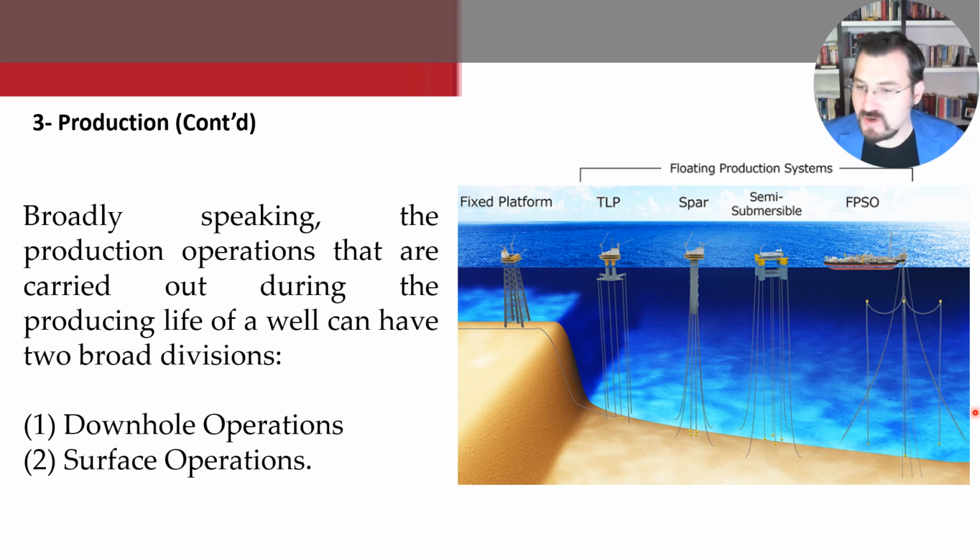For example, let's give an example with a new technology material. If you are dealing with a multi-phase flow meter in the surface operation, the subsea version of it is totally different compared with the phase tester, for example, Schlumberger's phase tester, which they are using on the surface, onshore. It has a totally different structure, and it has a much more closed loop structure. Closed loop structure, so you cannot do any maintenance from the outside directly. It's all complicated and has a closed section. All parts are closed, so specialized people have to come to the offshore platform, and if a fix is needed, then they do it in place.